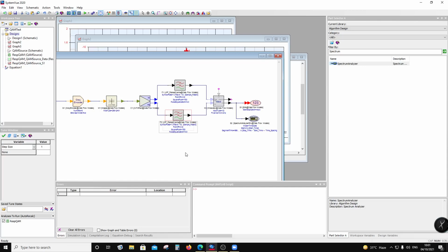What is a MIMO or a massive MIMO is basically you take a high-speed stream of data, ones and zeros, split it into sub streams which are going to be slower, and then you are going to modulate carriers with those substreams, and these substreams are uncorrelated substreams. The data is uncorrelated. So when you modulate these carriers or subcarriers with these substreams and transmit it, the entire envelope is going to see all kinds of noises and channel related distortions and things like that.